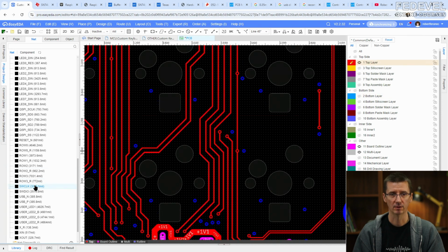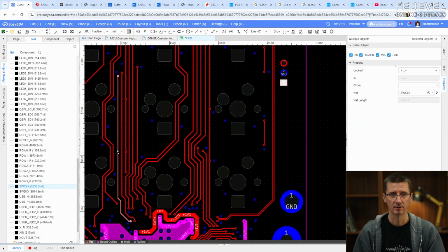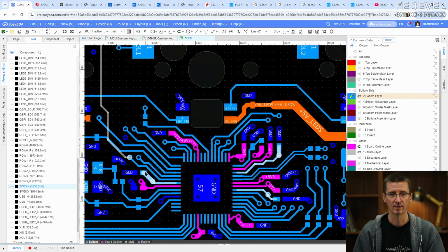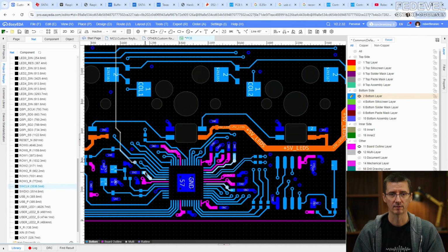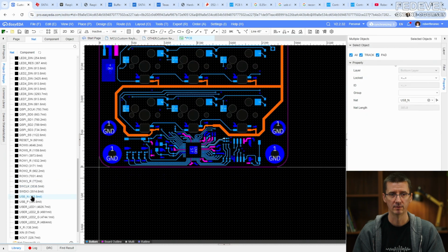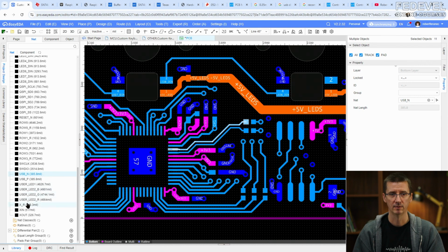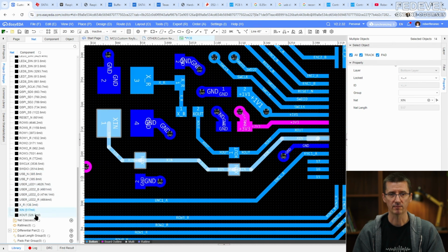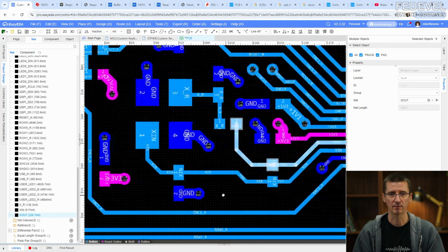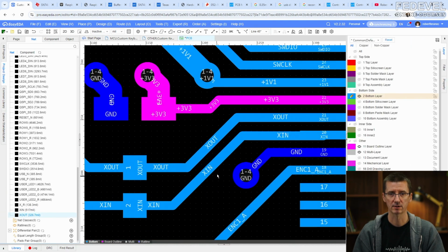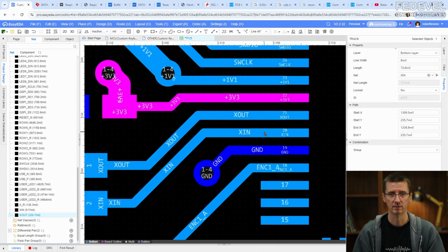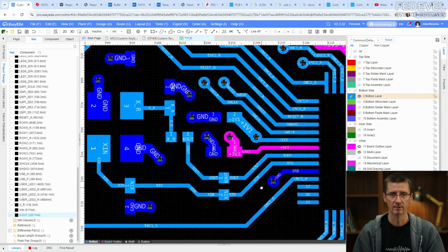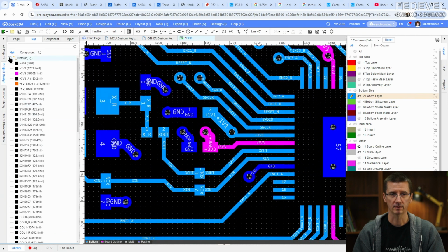This is also clock. Lot of space around this track, so that's good. USB and crystal. These are all very important tracks. Double check how they are routed, what is close to these tracks. Okay.